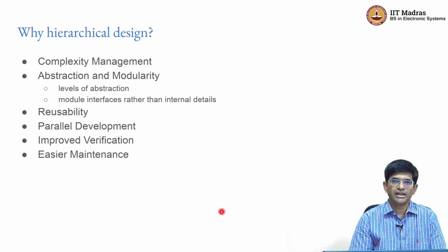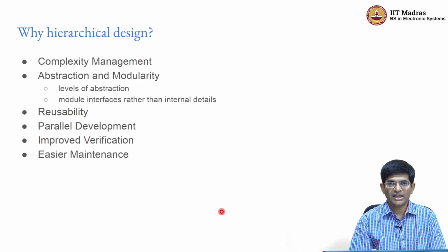For example, if we can say that our CPU is going to follow the AXI bus protocol in order to communicate with memory as well as other peripheral devices, that frees up our choices of what kind of devices we can build, and every other device just needs to be built in such a way that it's now compatible with the AXI bus standard, right. So this is what I mean when I talk about a module interface. The interface is this bus interface, which basically tells us that the CPU can talk to any peripheral provided that peripheral follows this particular bus standard.